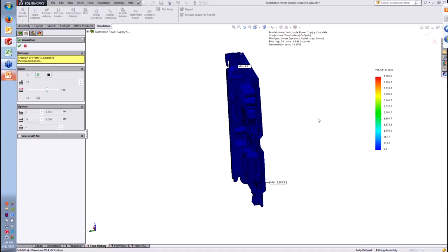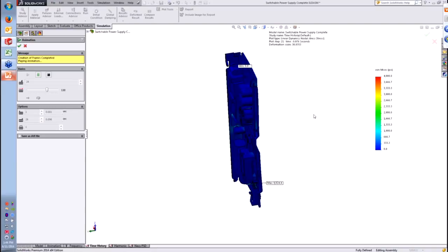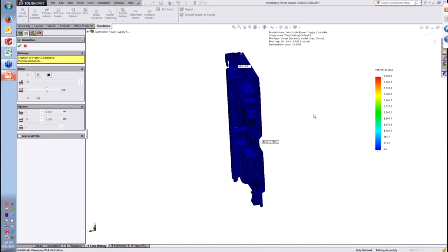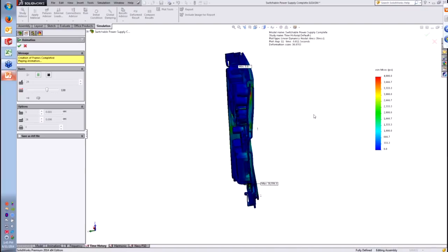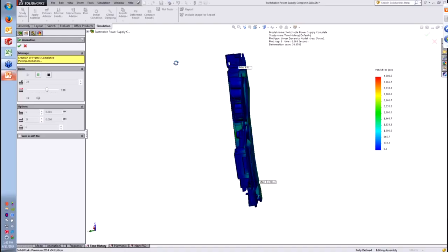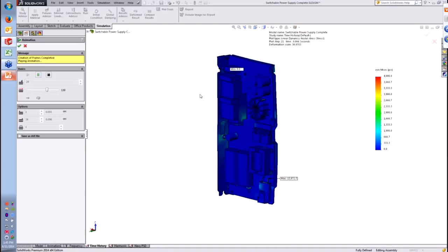But as you can tell, the first part of the impact where we're looking at this, of course, very slow motion, you're seeing the board kind of flex, and then it snaps back and vibrates a little bit. That would be when the vehicle or whatever it is has collided into the wall and then stops. And after it stopped, you'll get sort of that whiplash effect where it snaps back and vibrates. And because of the damping ratio we put in, we can see that the vibrations slow down rather quickly and damp out.